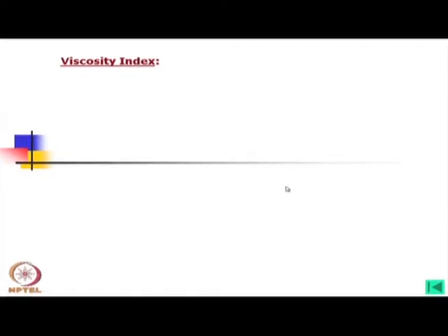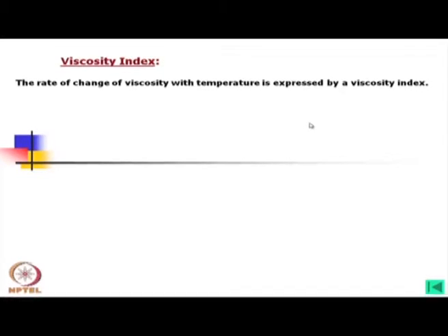Now, one important factor is the viscosity index. What is it? The rate of change of viscosity with temperature is expressed by the viscosity index.